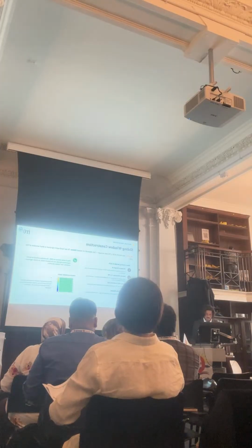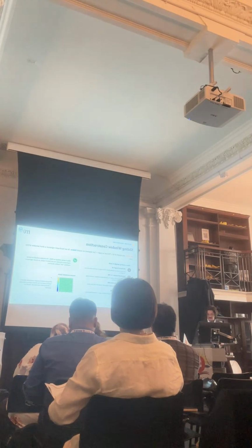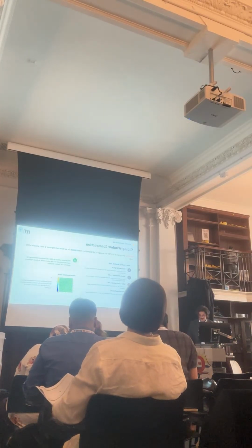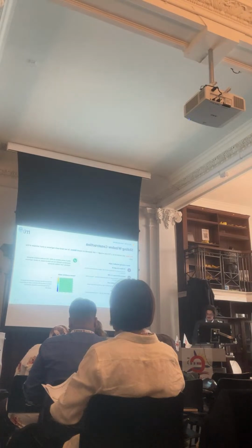This is basically the heart of the method. The key idea in sliding window construction is that one instant of the signals is not enough for the state of charge, because state of charge reflects the recent history. So for each step, we stack the previous window samples for all three signals into one flat feature record. The label is the state of charge at the end of the window. Why does this matter?